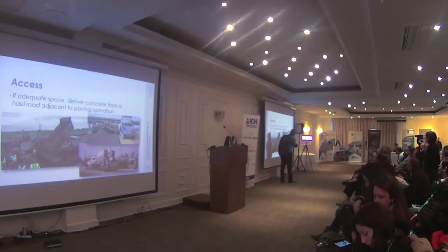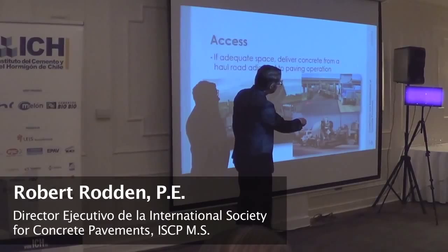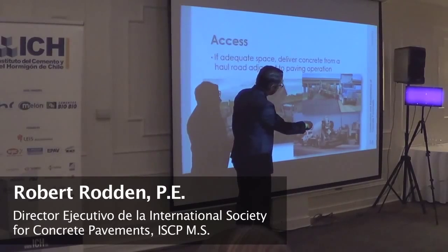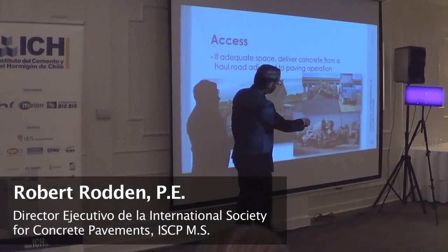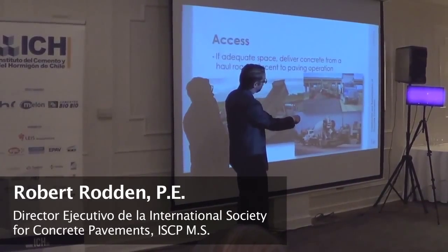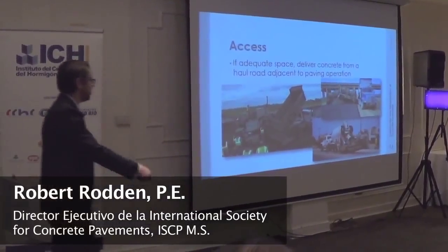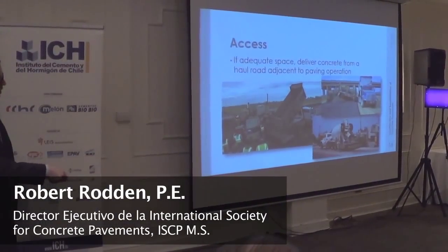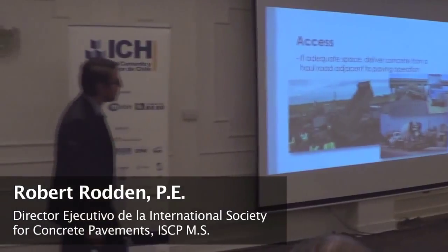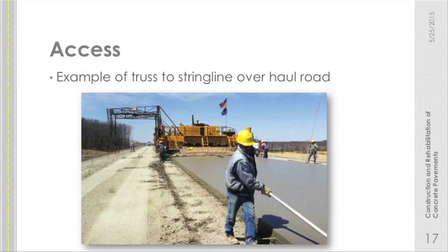Here we have a placer off to the side, which just has a conveyor and moves the concrete back and forth. What they're doing right here is bad. It's too high of a pile of concrete. It should be distributed as evenly as possible. Of course, with ready-mix trucks, we have chutes on the trucks, or we can use a placer spreader here. So they have another conveyor system.